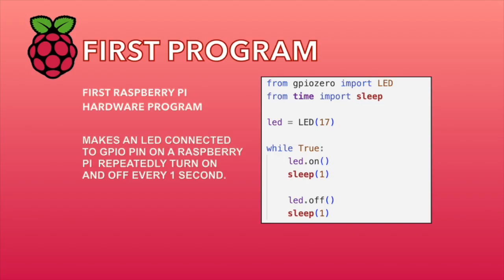That's the complete circuit. The resistor is critical. Without it, too much current flows through the LED and it burns out immediately. With a resistor in place, the current is limited to a safe level and the LED glows properly.